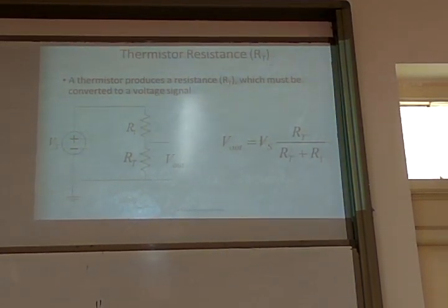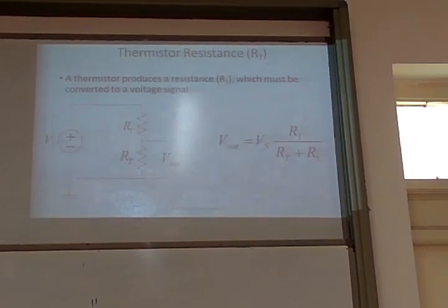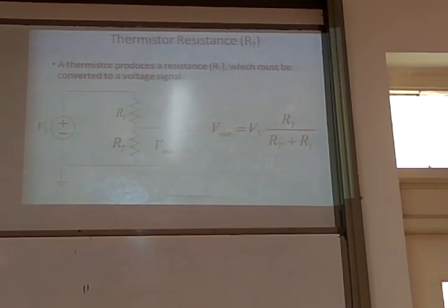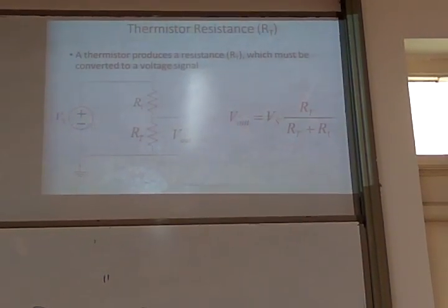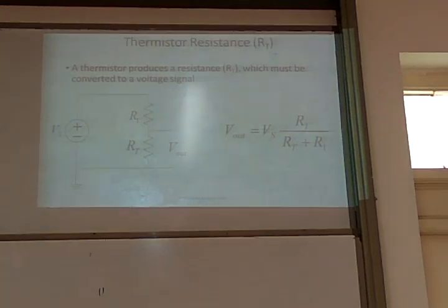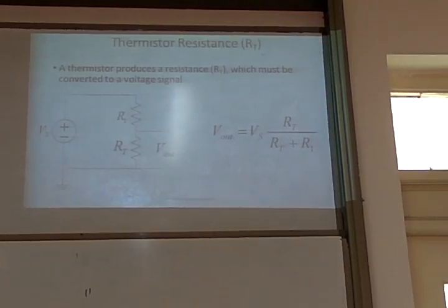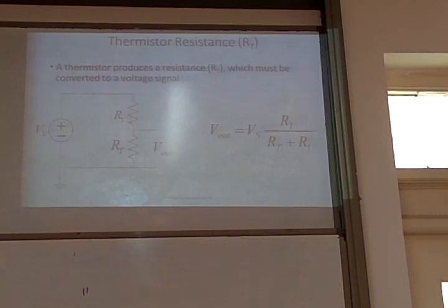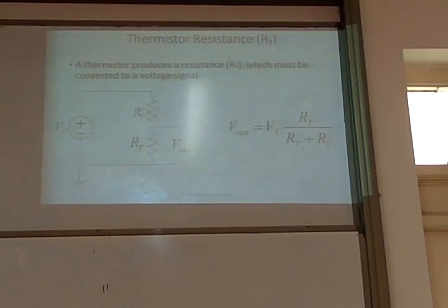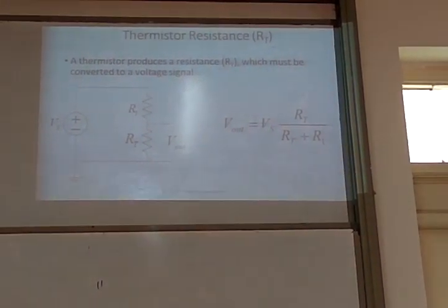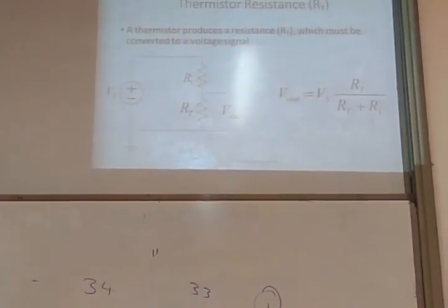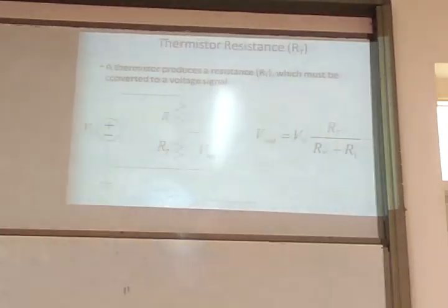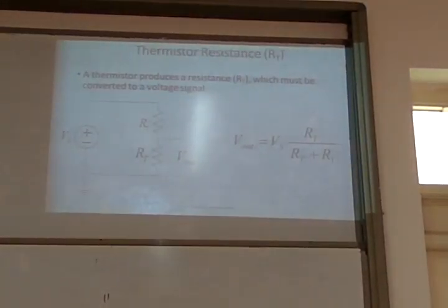Suppose you have some 3 volts here. The temperature now is some 37 degrees Celsius. For that, you get some voltage here: 3 volts, 3.5 volt, 3.2 volt, some volt. How to convert this 3.2 volt to that 37 degrees Celsius? If it is 40 degrees Celsius, you will get a corresponding voltage. We don't want to read that voltage. If 40 degrees Celsius is the actual temperature, we want 40 in the display unit, so that we can note down it is 40 degrees Celsius.